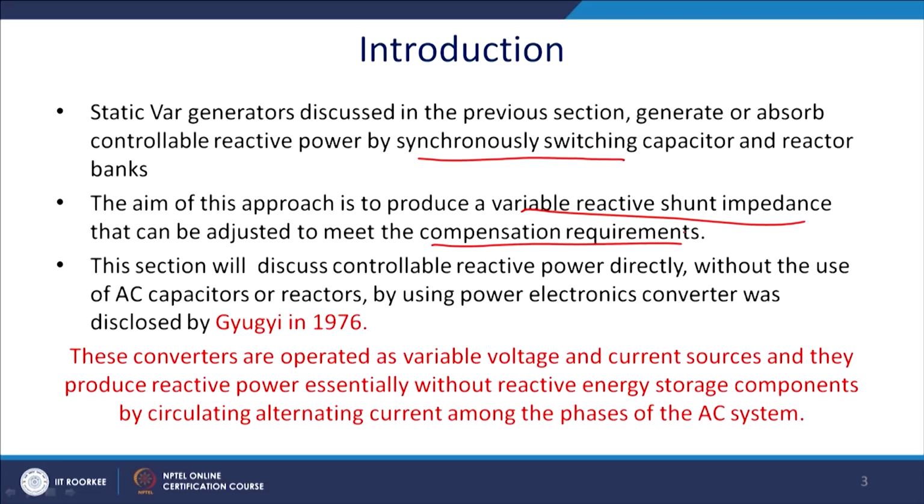So, we change, for real power generally, P equals sending end voltage times receiving end voltage divided by X, into sin delta. So, we generally change the value of X to change the power handling capability as well as the reactive power handling capability and the voltage regulation. And this section will discuss controllable reactive power directly. We will not introduce any impedance, we rather control the V2